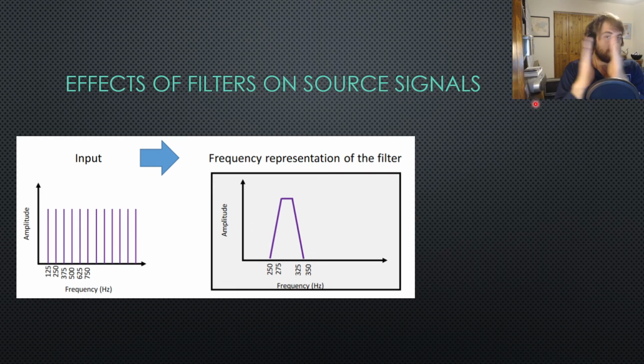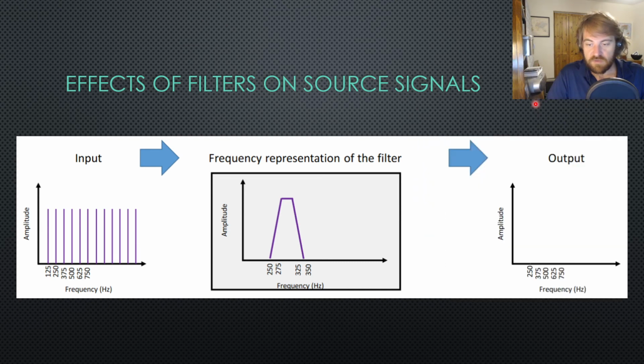All right. Now it's a little narrower. Still got some steep onsets and offsets. But it's a little narrower. So we would expect less to pass through, right? So go ahead and pause. And here's the answer. Hey, absolutely nothing passes. But why? Well, look. So we've got 250. This filter is at 0. Nothing is passing at 250. And then it's allowing things to pass completely from 275 to 325 back to 0 at 350.